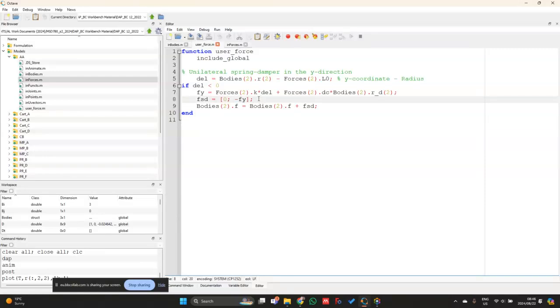In this case, it makes more sense that you know the spring stiffness and you know the suspension system's dynamic properties, and you want to perform a forward dynamic analysis, and you want to measure what the actual displacement or the coordinate of your wheel is going to be. So this is sort of a pure example of a forward dynamic analysis. An inverse dynamic analysis I don't really think would be appropriate for this type of problem, because we can't really predict the actual motion of the wheel, but we do know the properties of the springs and the tires.